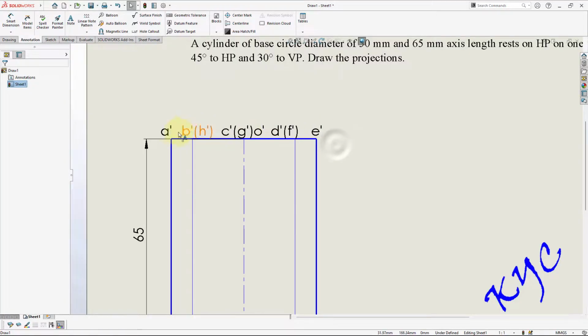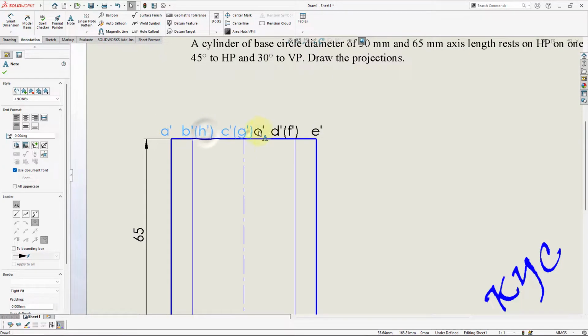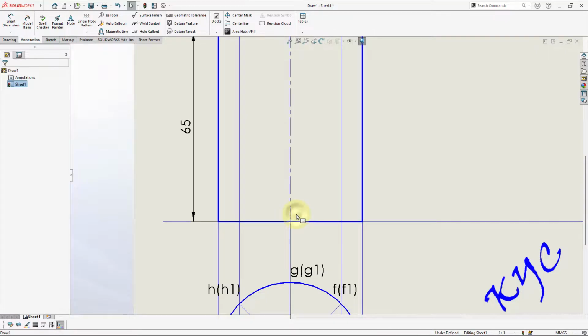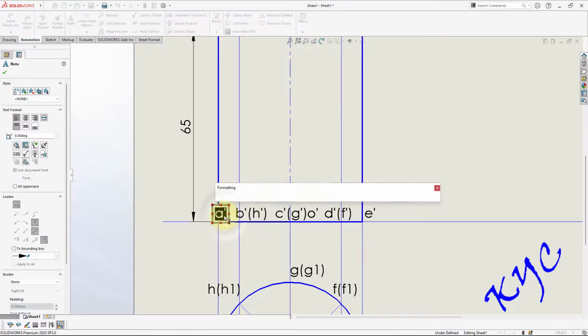After this, use the Control key and select the multiple text. Control C for copy. Then zoom into this location. Click where you want to paste. Control V. So now I should keep adding one.